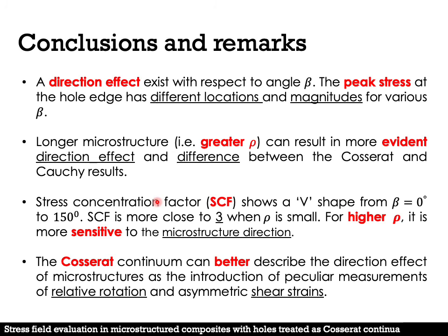The Cosserat continuum can better describe the effect of the microstructures, as it introduces peculiar measurements such as the relative rotation and the unsymmetrical shear strain, because those measurements show very different behavior among different transformation angles beta.